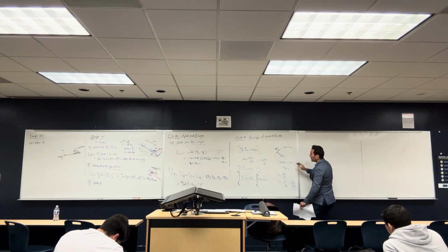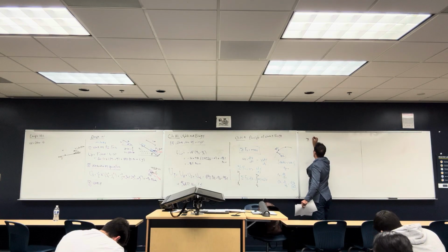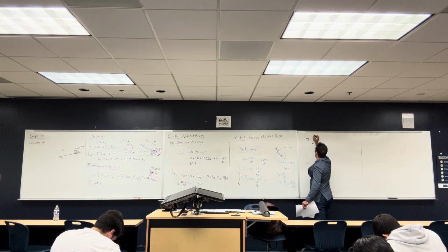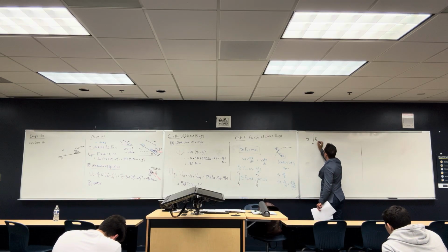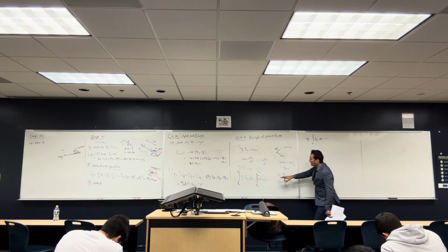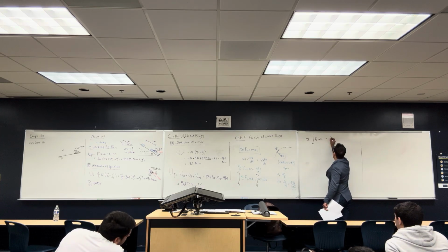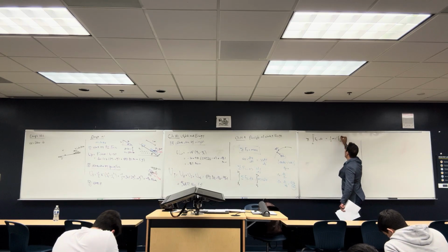Okay, so I can take the summation outside of the integration and integrate all the forces from s1 to s2 of F tangent ds, and this is going to be equal to, if I integrate m v dv, half m v squared, with the boundaries of integration from v1 to v2.